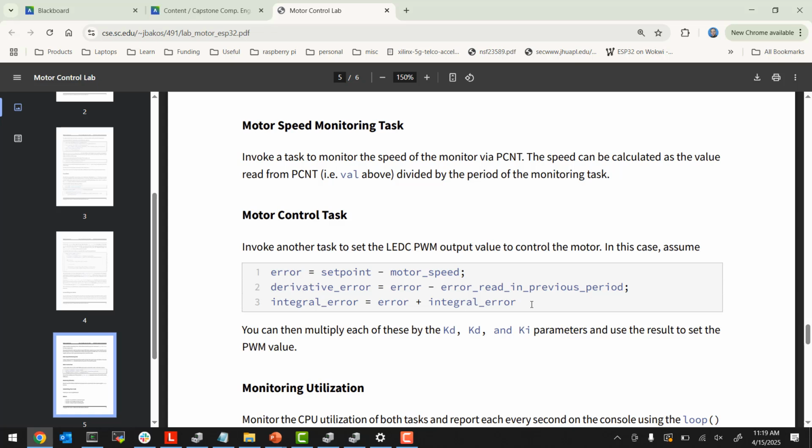I think Alex said these motors don't go that slow, right? Because these are not geared. The lowest you can go here is about 60 RPM, so that's 1 rotation per second. If you go any slower than that, you're going to start having problems. Yeah, I'd aim for that or maybe 120 RPM. And you can power these motors on anything from 12 to 24 volts.